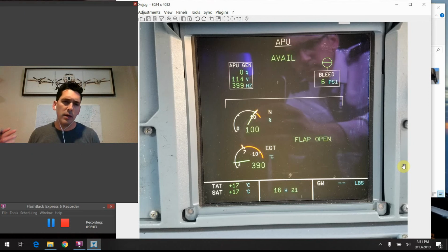When we first bring power onto the airplane, there's a substantial amount of time where we use the ground support equipment to bring power from the jet bridge, and most of the time we're getting preconditioned air from the jet bridge as well. But about 10 minutes before we're ready to push back and get off the gate, we'll turn the APU on and switch all these systems over to the internal sources, in other words the APU.